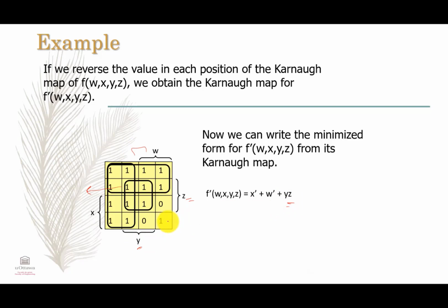Now this one is the tricky one. Remember I told you, the Karnaugh map, even though it looks like a cube, is like a cylinder here. So that's why I will be able to group these for Y, because look at what is the code for this cell? That is 0 0. What's the code for this cell? The code for this cell is 1 0.